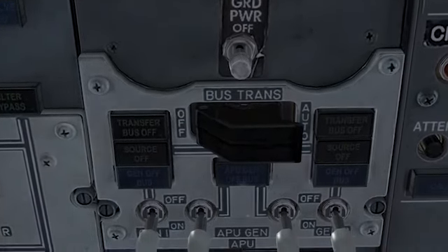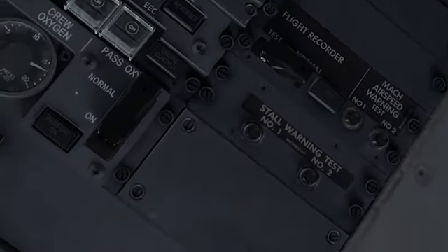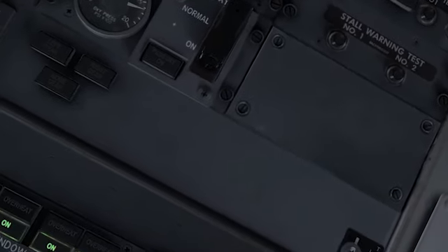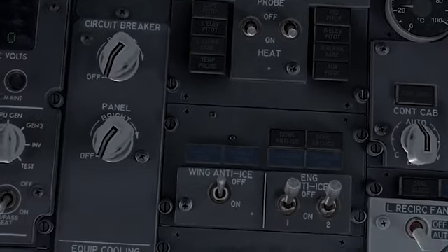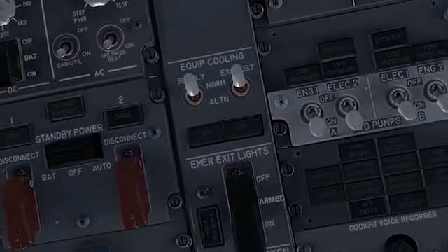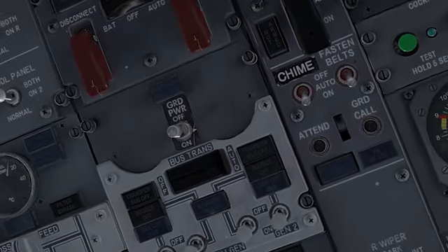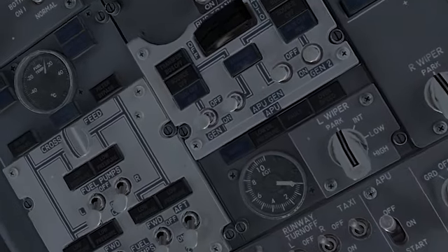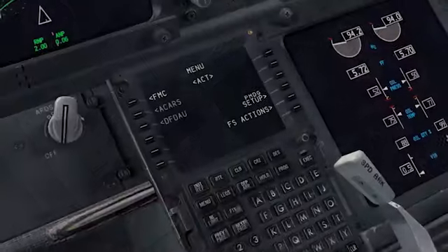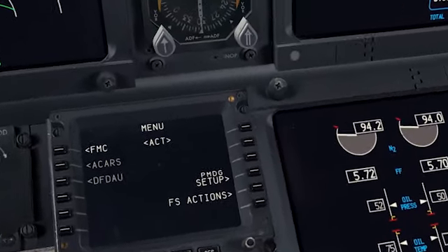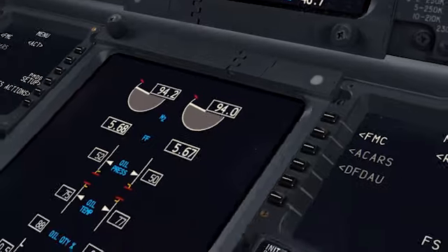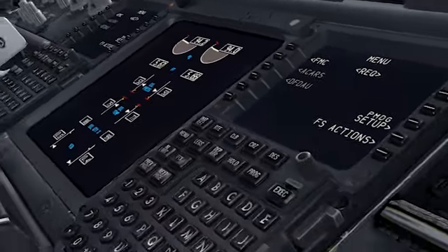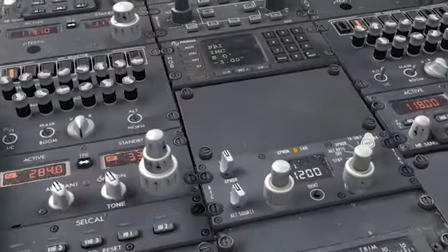Worth mentioning is that the entire electrical system is also protected by circuit breakers located behind the first officer's seat. These circuit breakers jump when there's a problem within the related circuit and may be reset on ground by maintenance personnel. Flight crew may also reset a tripped circuit breaker if it becomes imperative for safety reasons. A cooling time must be allowed between successive circuit breaker resets.